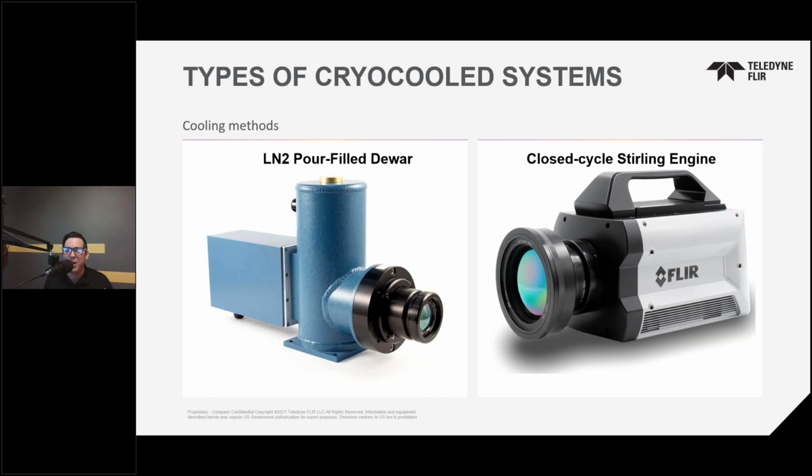With a cryo-cooled detector, though, each pixel is going to be a unit cell that has its own integration capacitor. So we saw before on the bolometer side where we're heating up those detector elements and reading a change in resistance. These detectors, they're designed completely differently. We're capturing that energy in this integration capacitor.